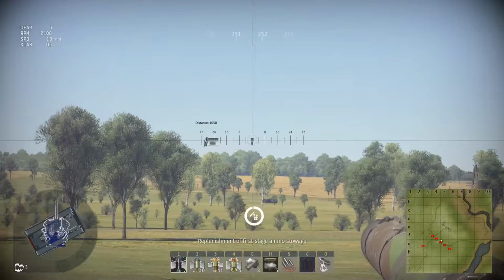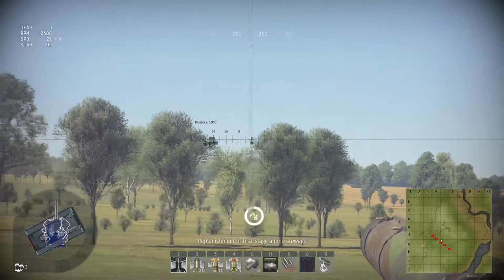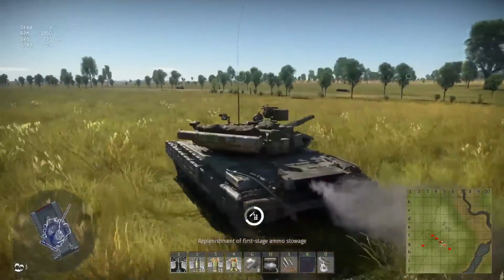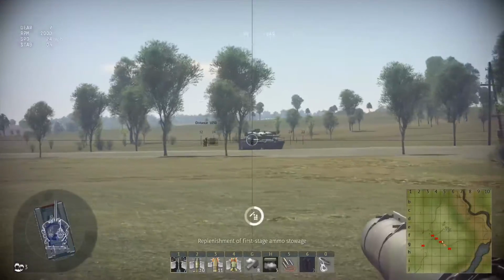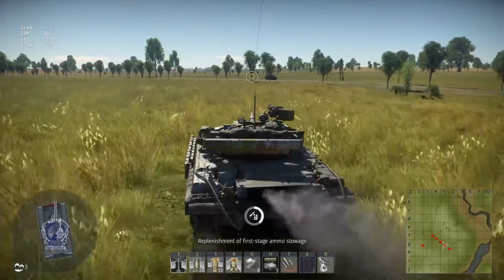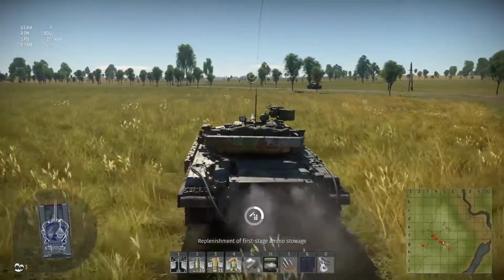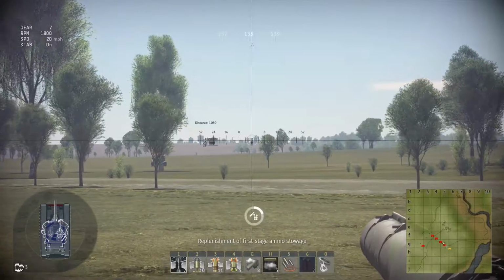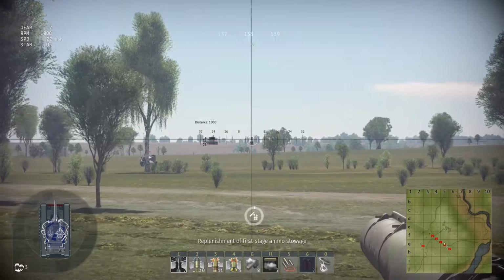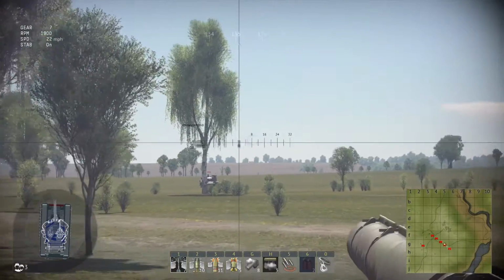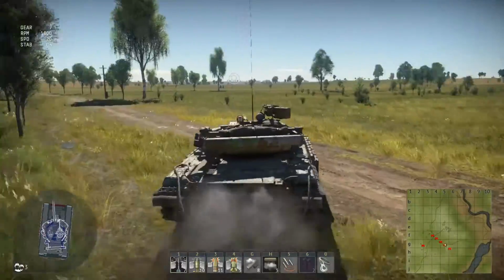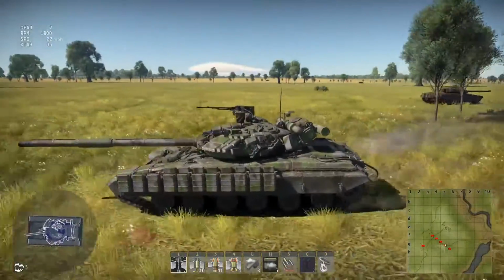But in the meantime, these horizontal markings basically measure milliradians of angle. If you imagine having a protractor stuck on the front of your tank turret with all the lines sticking out for 180 degrees, obviously the further away you go, the wider 1 degree becomes, and this is a scale to measure it, and it's fixed and standardized across all gun sights.